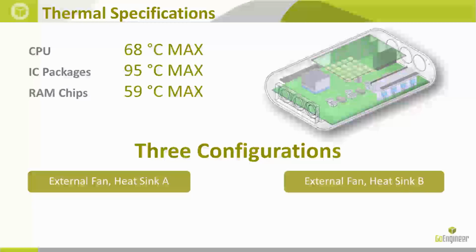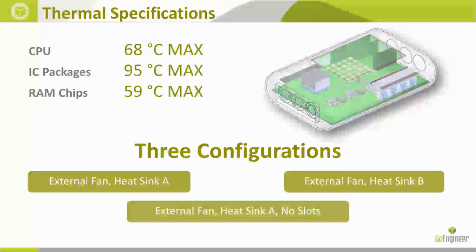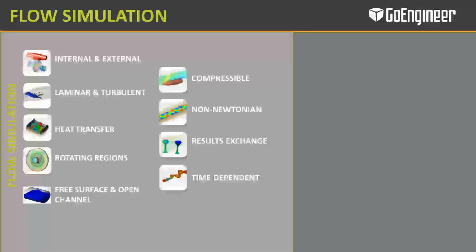We also have a second heatsink configuration where we have cylindrical extrusions as compared to slits like they are right now. And finally, currently you don't see the slots modeled on the very top of this enclosure, which allows heat to go out on the top. Do we need those slots or not? So we will go ahead and evaluate them as well, and kind of evaluate the performance of both of them.